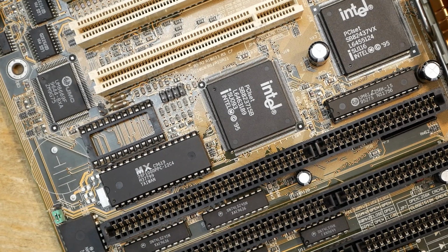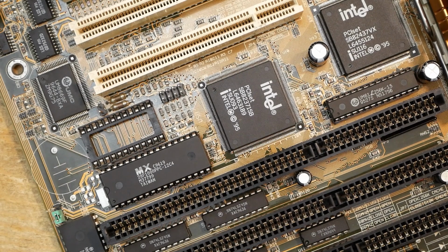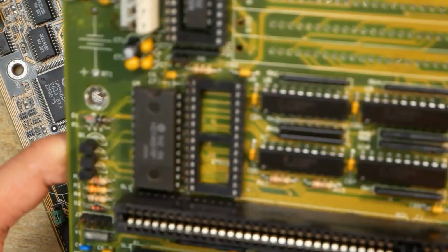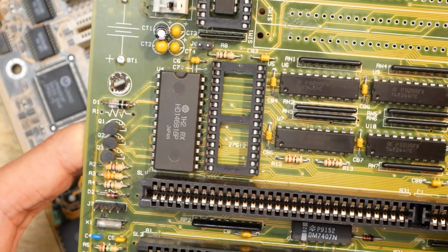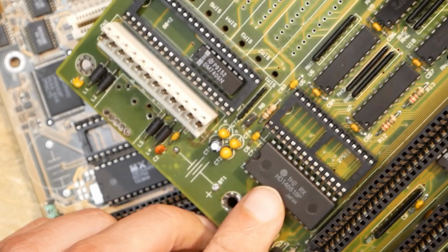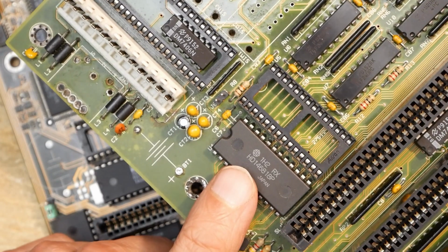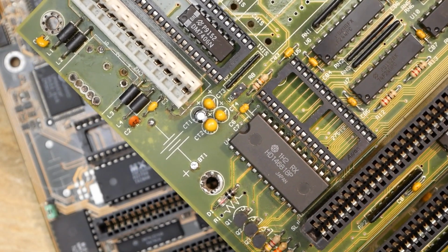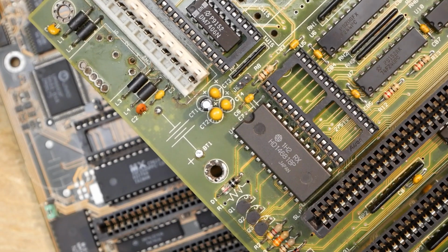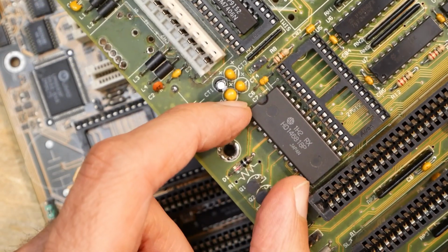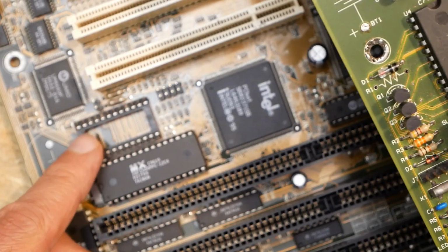And so we come to the actual point of this video, the question: which chip is the right one and where to get it from? For obvious reasons, those chips have not been produced for many years. It is not too hard today to find a Motorola MC146818 or a compatible Hitachi chip on some damaged 286 or 386 mainboard. However, they will not work in Pentium mainboards, since those are designed for integrated solutions, as I explained before, and an old Motorola chip has a slightly different pinout and needs additional circuits.